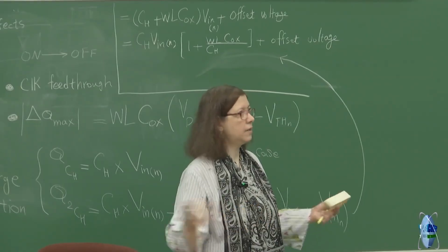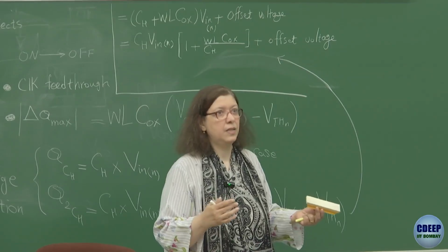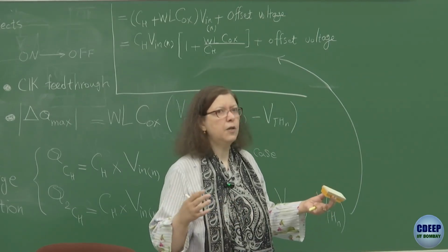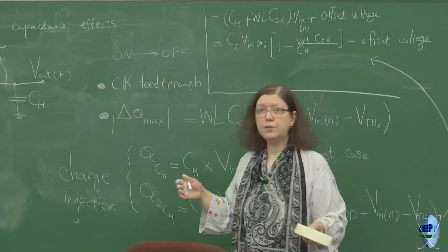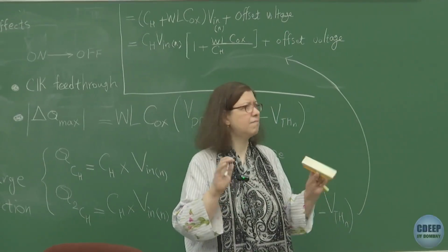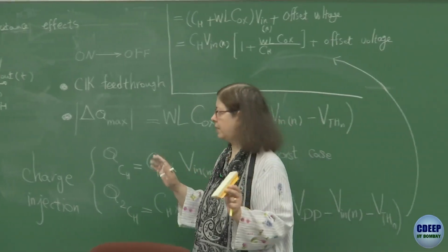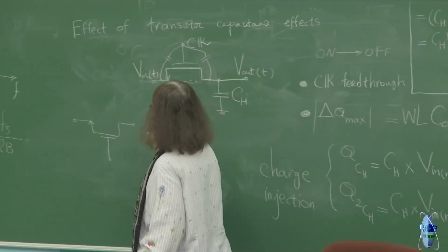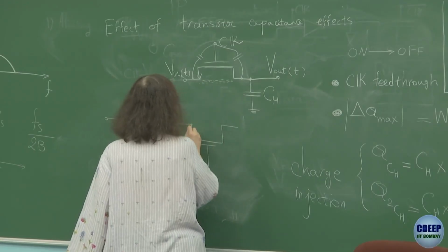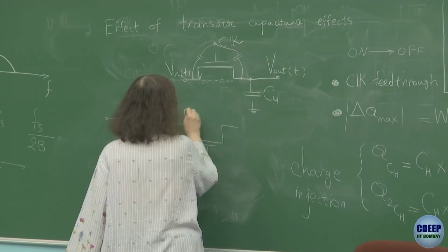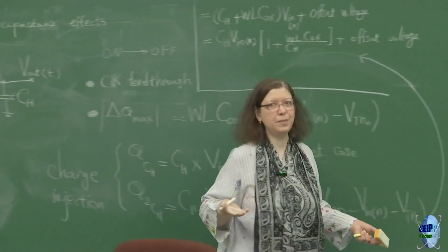When it turns on, it brings the charge to the channel from the same terminals, specifically the source terminal. Why not add a transistor which will turn on when this transistor turns off? And that transistor, we don't want to do anything. We just add it, it's called a dummy transistor, to just create a path for the charge. That's it, no other effect. Whenever you want to create a dummy transistor, it's enough to short source and drain. Indeed, it becomes like a dummy. It can't do anything.